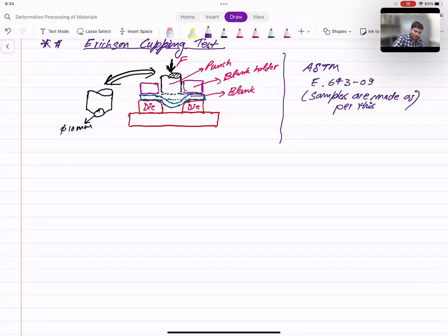The drawing here is carried till fracture, till a crack is initiated and the material fractures. So there is a possibility of formation of two different types of cracks here. Either a circumferential crack may form, which will be circular in nature, formed along the circumference, and the other crack type may be a flat crack, which may form anywhere on the drawn surface. If we try to draw them, it will be something like,